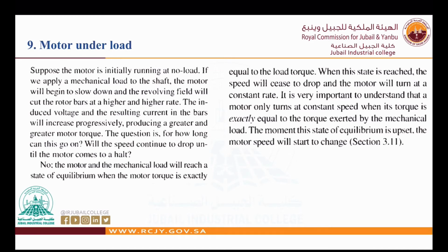So the moment the state of equilibrium is upset, the motor speed will start to change. If we don't have this equality between induced torque and load torque, then the speed is going to change, either by increasing or decreasing.